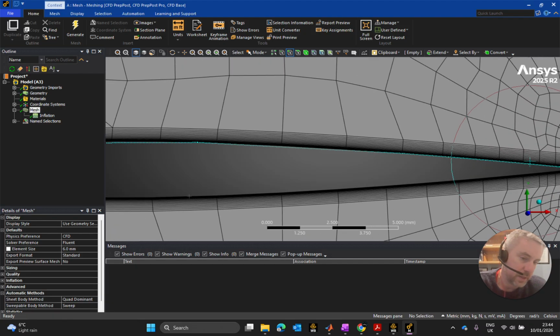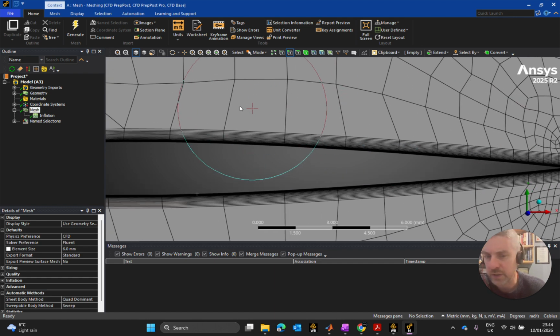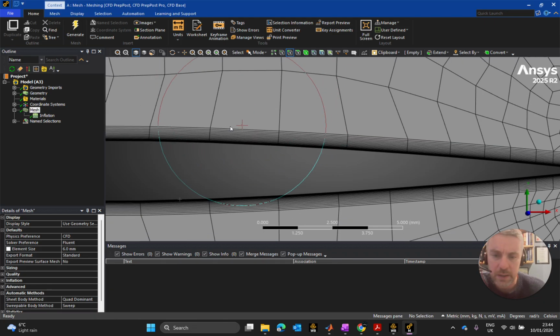Now back here, things are just going to get very bad as far as analysis goes. We have no real provisions in here to adequately look at wakes or any sort of flow coming off after the airfoil. And even up here, we'd need to make this somewhat better. Even though it's unstructured, we'd want to make that better.